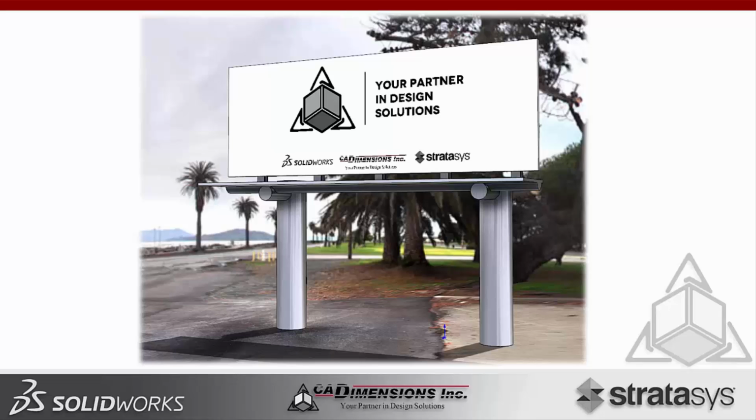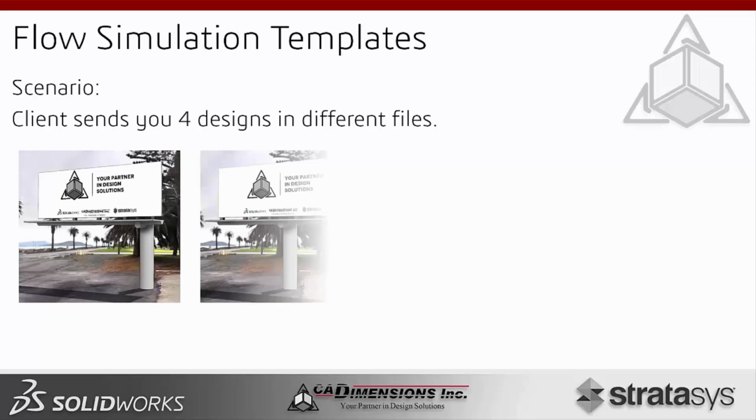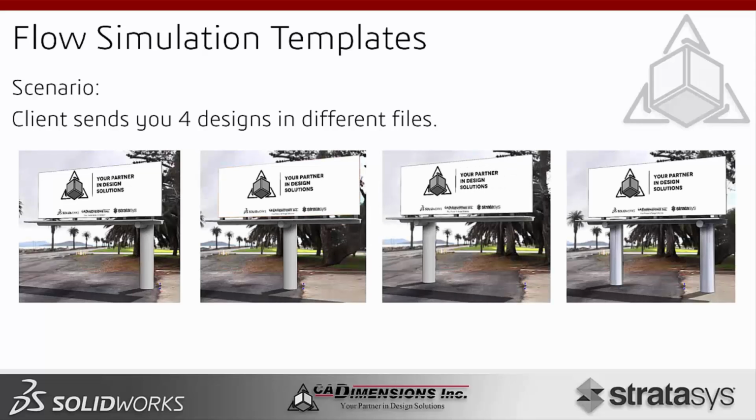Today we're going to be talking about flow simulation templates. Here's a situation. I'm running a flow simulation on 4 different billboard designs, and my supplier just sent me 4 different files of the billboard designs, the different design iterations. Well, in SolidWorks, it's easy if they were created using configurations. It would be easy to just copy the flow simulation study from one configuration to another. It gets a little bit more involved if they're different files. Today I'm going to show you how to create templates in flow simulation so I can very easily make sure that my boundary conditions are the same from one file to the next.